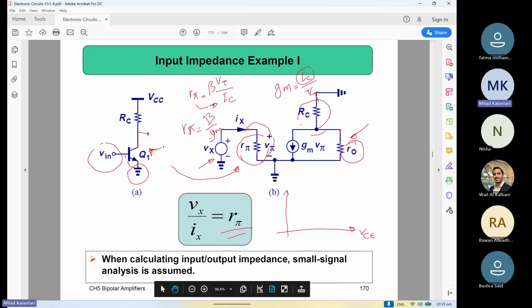If you sweep V_CE in the DC curve, ideally you would like to have a constant current source. If you change the voltage across the collector-emitter of an ideal current source, it should not change the value, because the current is not dependent on the voltage across it.